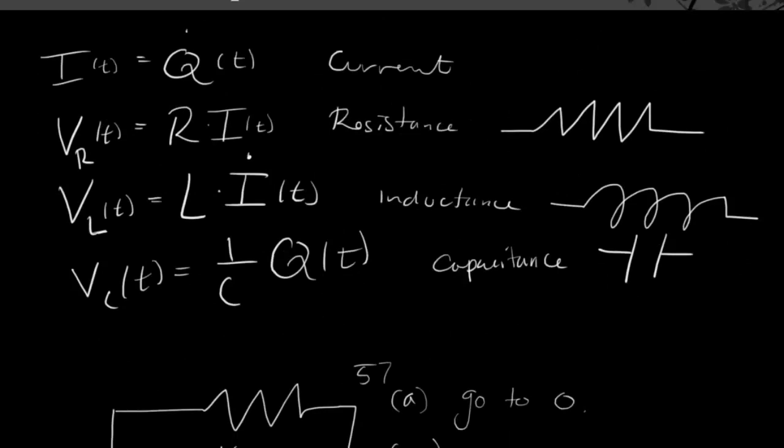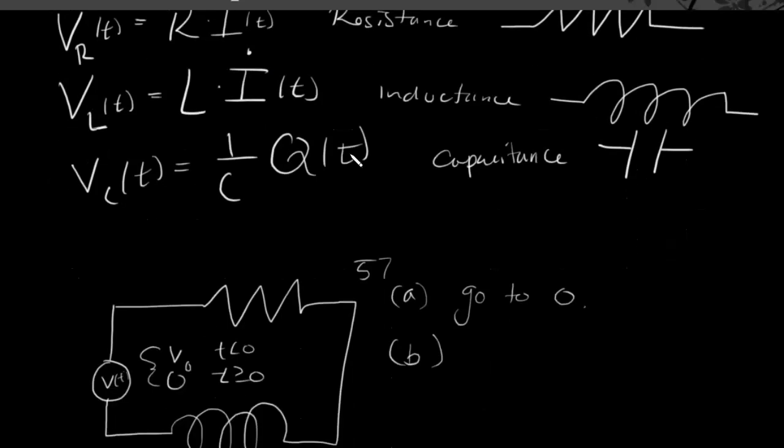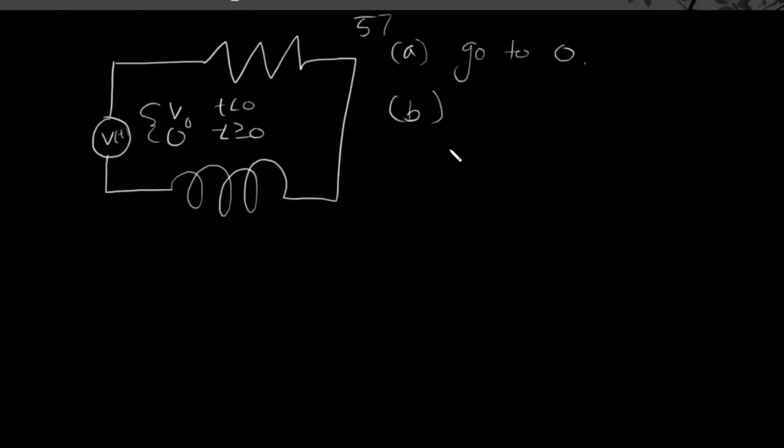When you have the resistor, you would add R times I, right? So that's when you have a resistor. When we have an inductor here, we would add L times I dot. So let's write that down here. We have L times I dot. I'm going to write that first, just so we have the derivative showing up first, plus R I, and that's going to be equal to 0, since we're not going to be plugging in any voltage values, right? Because this is what we call a homogeneous equation.